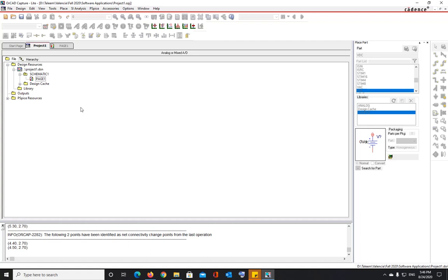If it finds duplicate names or values, I believe that it will also generate an error. So the best way to do multiple circuits, for example, if I give you a homework that has 5 circuits, 5 exercises, then instead of putting new pages under a schematic, put new schematics and one page under each schematic.